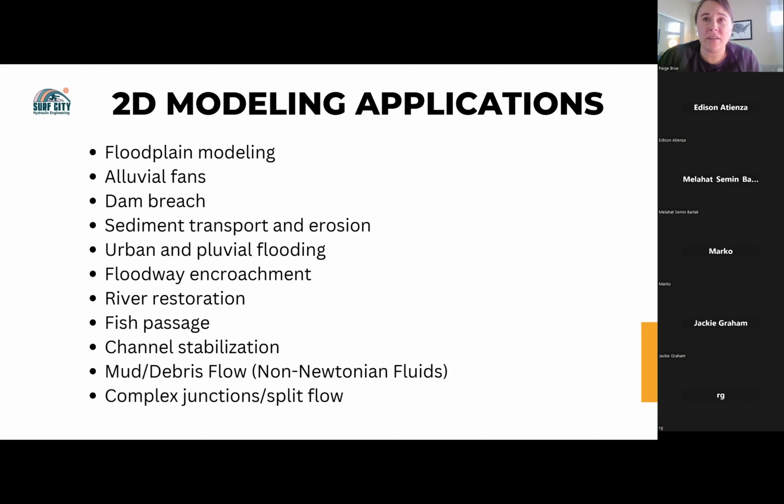And then you can't realistically get a very fine spatial resolution on that, so your results are kind of questionable in that way. A good workflow for that would be to put your rain on grid model in HEC-RAS, maybe use a more coarse DEM, and then get your hydrograph for the area of interest.